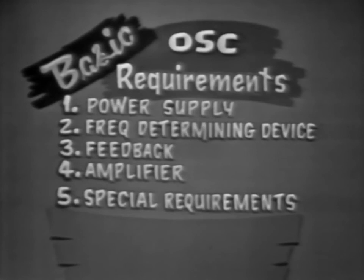There may be other requirements depending on the application of the oscillator, which you'll discover when you study a particular piece of equipment. But the main idea is that all oscillators are basically the same. So whatever the type or the name of the circuit, all oscillators will require a power supply, a frequency determining device, feedback, usually from an amplifier.